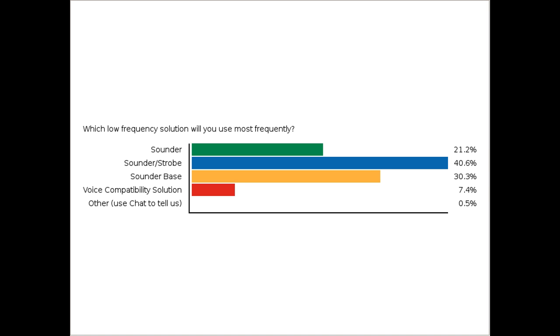So that's why you go through UL. That's why UL has these performance requirements. So they're in essence evaluating the products to make sure that they're meeting that square wave format and that it's meeting that harmonic profile centered around 520. So all you still need to do, and something that someone had asked me previously, is that there is still the audibility requirements for the sleeping spaces, so 75 dB at the pillow. So you still have to do that and prove that out, but you don't have to do any sort of verification of that low frequency format.